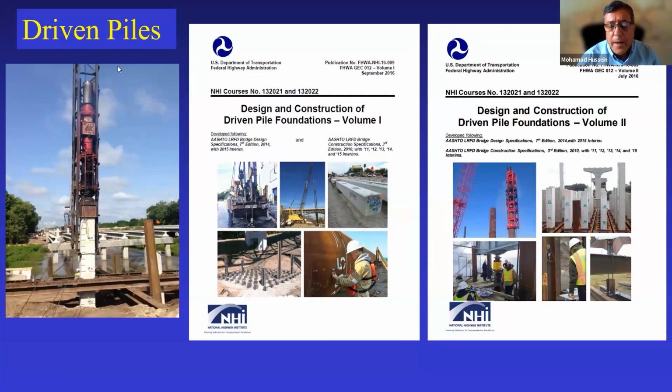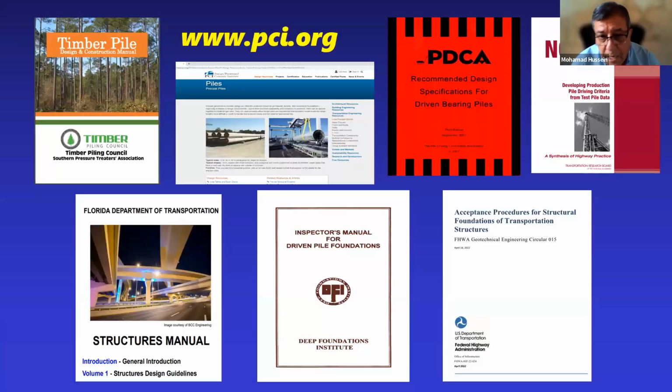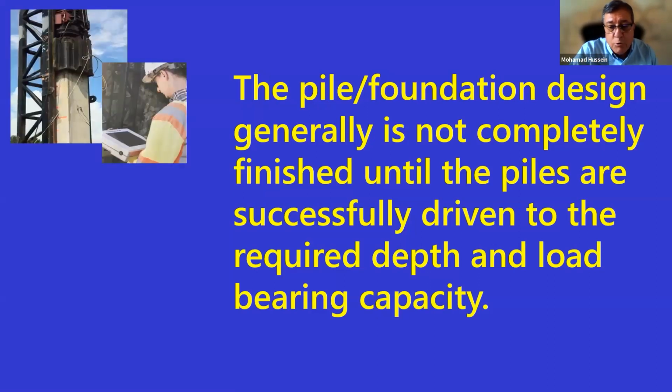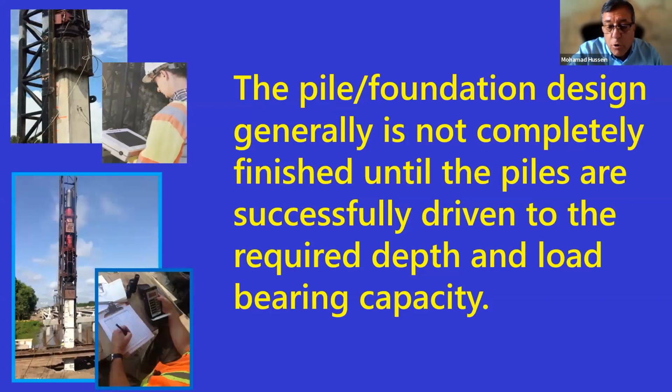A good reference I can suggest for driven piles will be the FHWA manual that can be downloaded for free if you just Google that from FHWA. That's highly recommended. Also, there are other manuals that one can use from the DFI and other organizations related to the design and construction and testing of driven piles. The bottom line is that a pile foundation design generally is not completely finished until the piles are successfully driven to the required depth and load-bearing capacity. For that, we typically use testing and/or quality control by inspection.